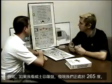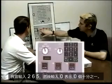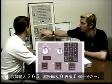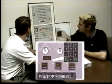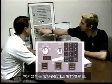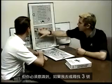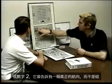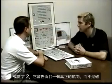For instance, if I looked on the whiskey compass and I saw we were doing 265 degrees, I would enter 265 and then 0 for 0 tenths. I can't read a tenth on that. And then I'd hit enter. That's going to come up here and give me my magnetic heading up there. You have to realize though that if I look for number 3 or number 2, it's going to tell me a true heading as opposed to a magnetic heading that I'm entering.